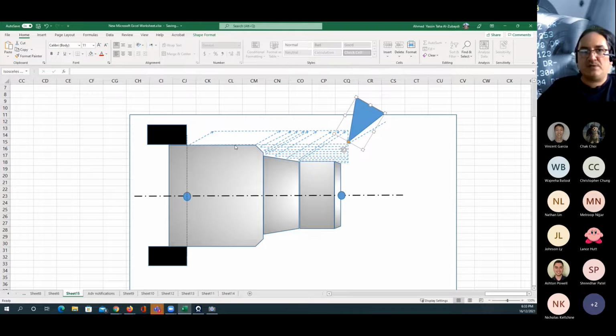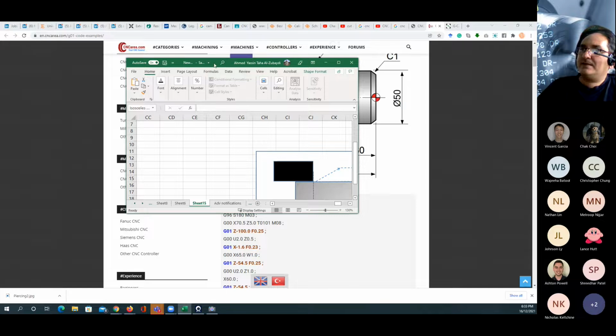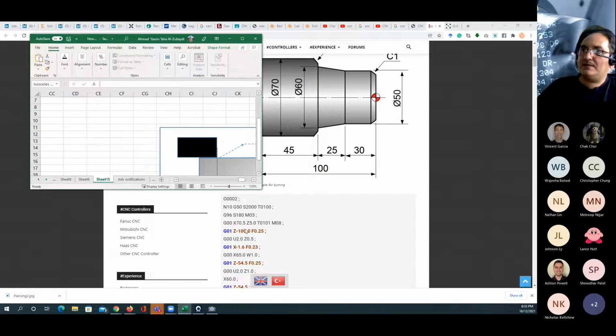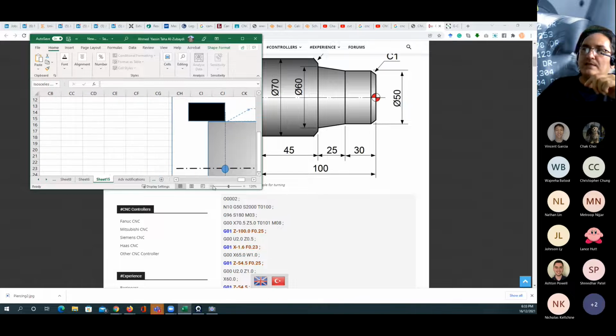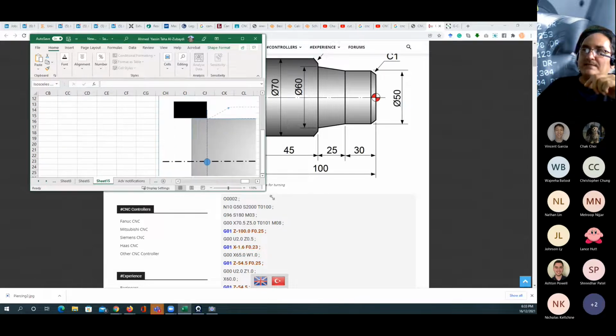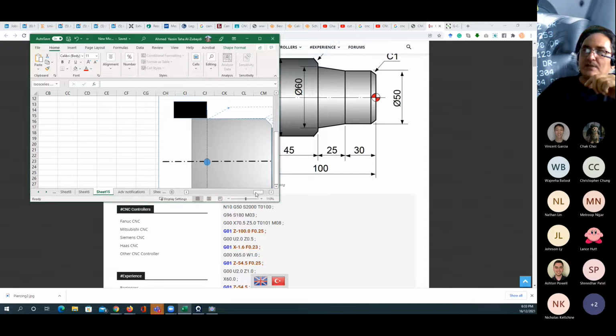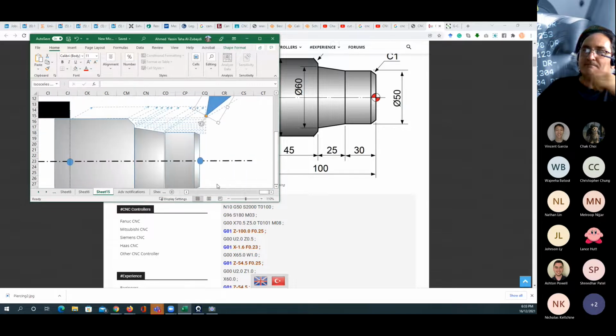When I say 0.25 millimeters, because I'm going to add here 0.25, it's going to be added on the other side as 0.25, and this will make it 70 millimeters in diameter. So just remember once again here, we're using the diameter as the X value, not the radius. So it's 70.5, Z is 5, that means it's going to be on the right side of the datum point, which is located on the face of the work part.